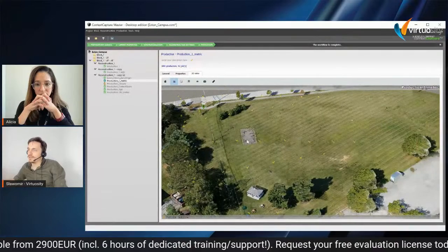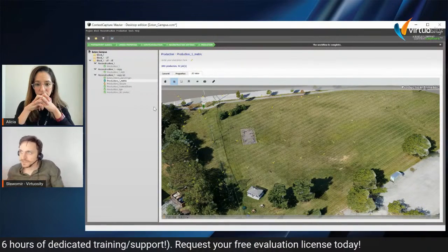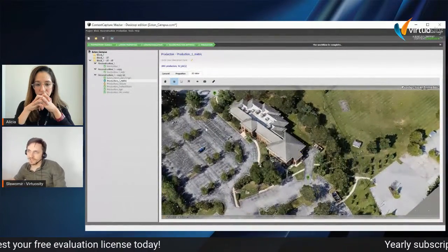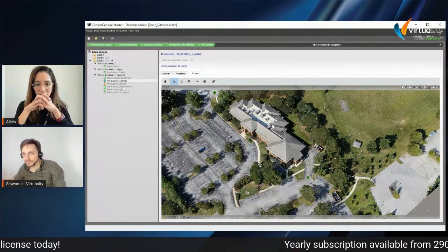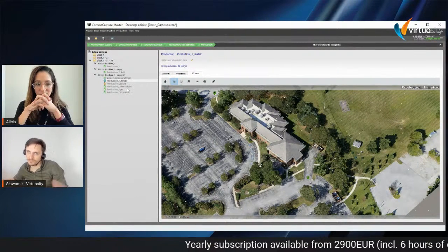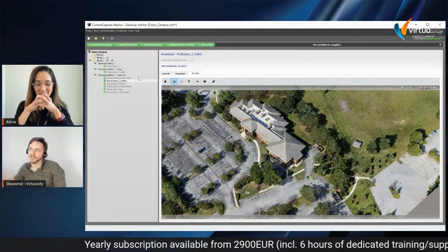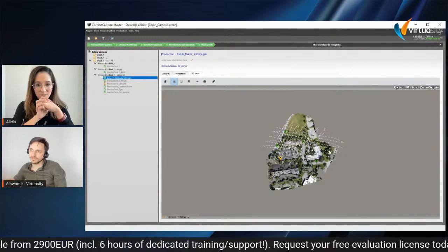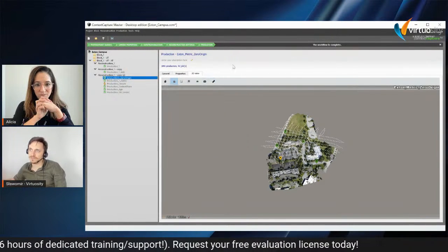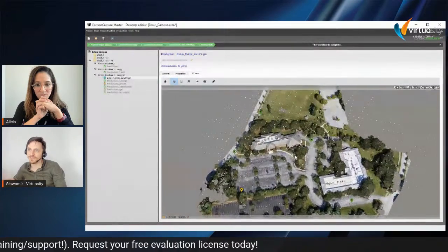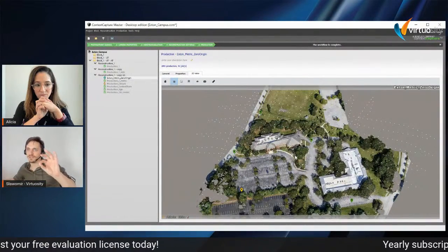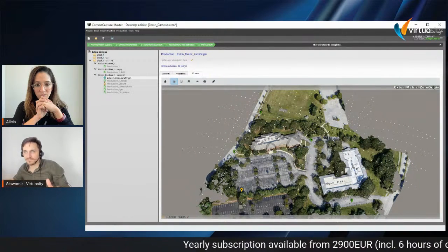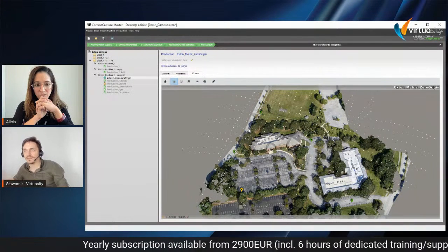In this case, there was rather more discussion of which units we have to use, because first the production had been made in imperial units. I had to change it to metric, so I created a new production, and after all we decided to just change the zero origin, because ContextCapture also gives us a possibility to shift the zero point of the project by some vector.